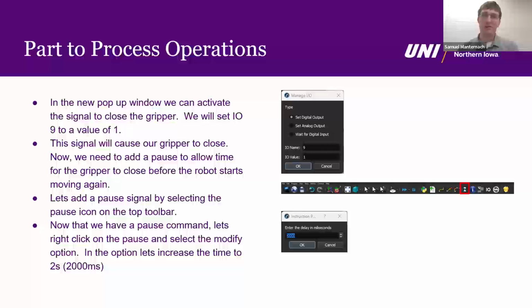So what we're going to want to do is also add a delay or a wait to our robot. If you don't send this wait command, your robot is just going to simply be moving through its motion while that signal is running and while the jaws are closing. This timing varies from robot manufacturer to robot manufacturer and where it happens in the motion. By setting up this wait program, we know exactly where that close is going to happen and how long it's going to take.